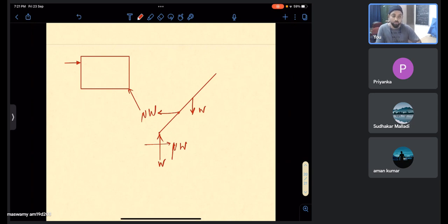Now, moment equilibrium, if you see about this point, mu W into this far distance is the overturning moment. W into this distance is the restoring moment. Can it ever happen that mu W can be more than W d? That is the essence of the question. So this will never happen. If you pull it with W d, you cannot overturn it. If you pull it beyond that, it will never lose contact because friction is exceeded, so it will slide.